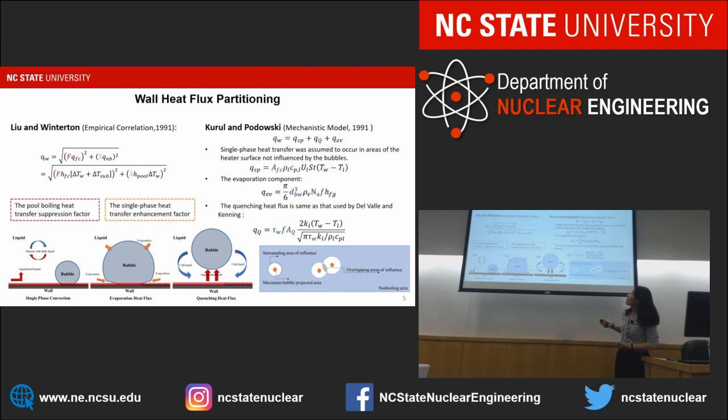The wall heat flux is divided into two parts: the pool boiling heat transfer and the single phase heat transfer. And the empirical parameter here is used to determine the contribution from each component. As we can all see here, it's not very physical.